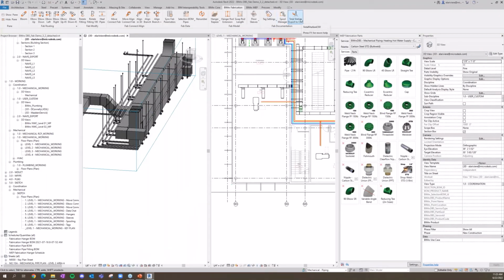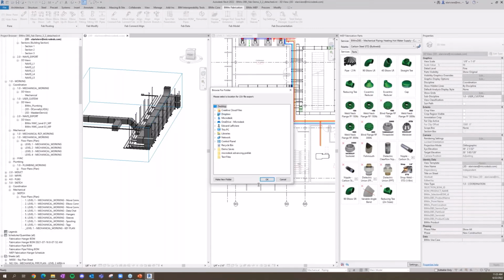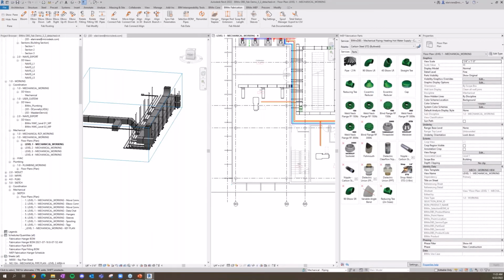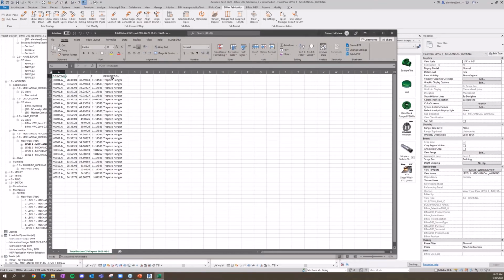And then when we're ready, all good and done, I'm happy with my hangers. We can do an incredibly quick export to total station. All it needs us to do is select those points. I like to do it from a 3D view, making sure I'm only seeing the elements I want. And it just generates that exact export we need, loads directly into total station. And if we want to see that Excel file very quickly, a quick jaunt to my desktop. In there we have that CSV opening up. And there we go, given a quick description, an XYZ location, and automatically numbering those points.